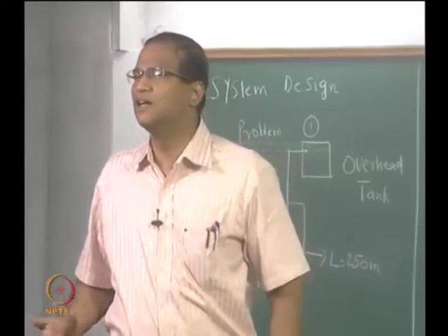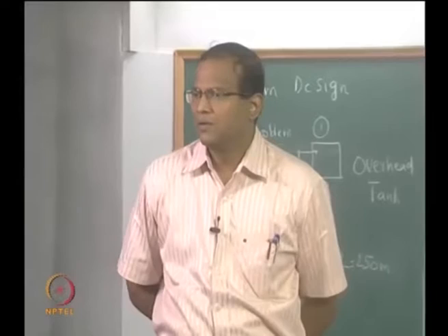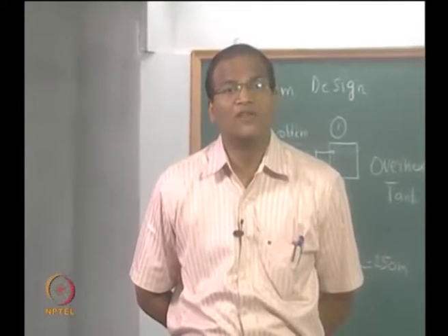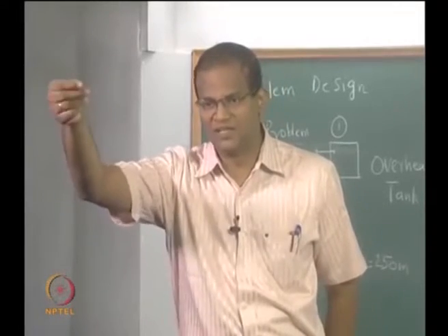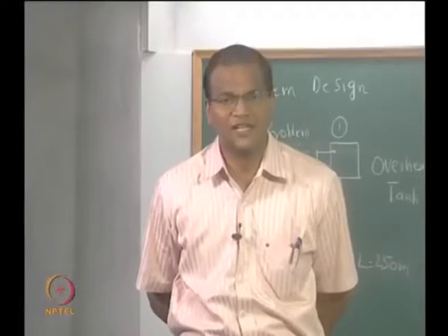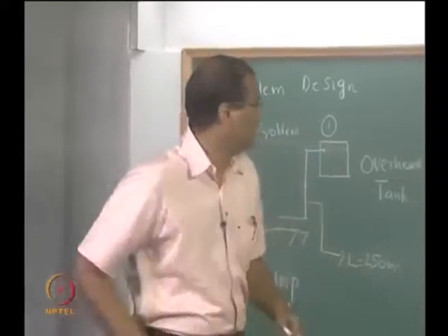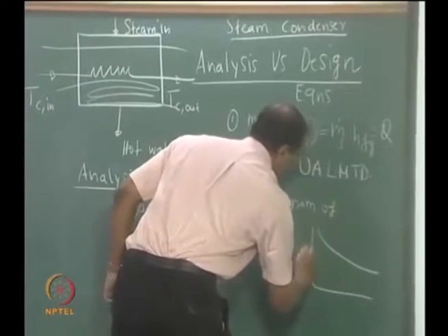Why will the heat transfer coefficient vary with time? Scaling, which is called fouling. Because of that, there will be a build up of biological matter and all these things, because of which the resistance to the heat transfer increases. The resistance to the heat transfer increases, the heat transfer coefficient will exponentially decay with time. Therefore, you may have a situation where you will have an H which is going like this.